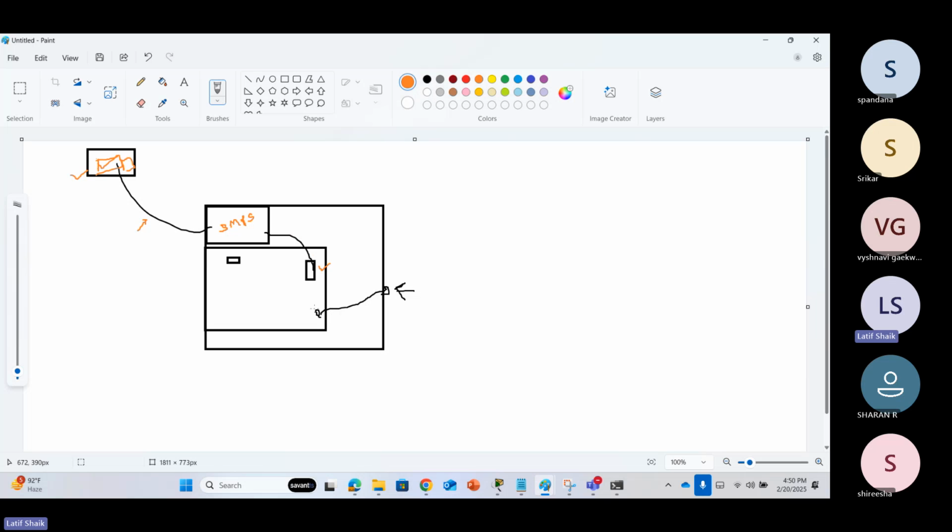Check the front panel connection, the front panel on the motherboard to front panel connection. Check this connection, and this power button also. Sometimes the power button is not working, and at that time also you are not getting power. Okay. So these are the different places you have to check. Again, you have to check the SMPS. I told SMPS, but I didn't check-mark it. I went to check-mark it right now, right? Why I went to it last, I will say.